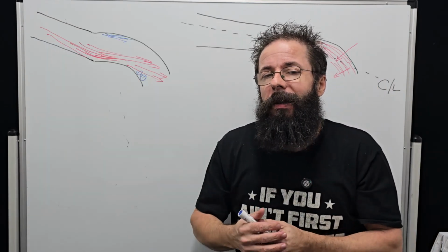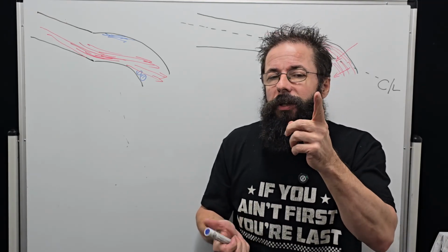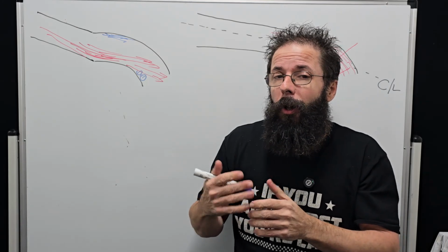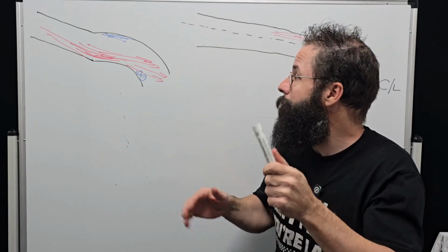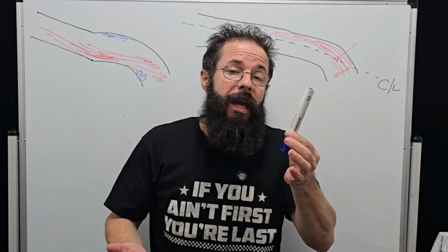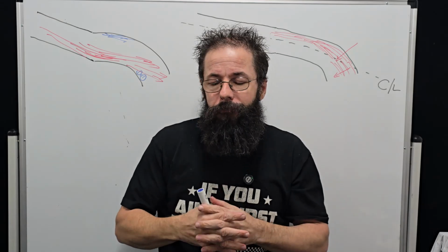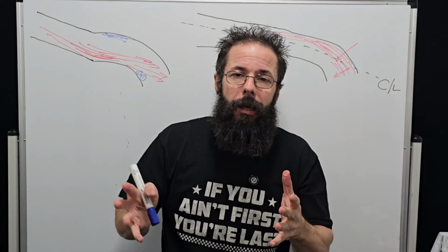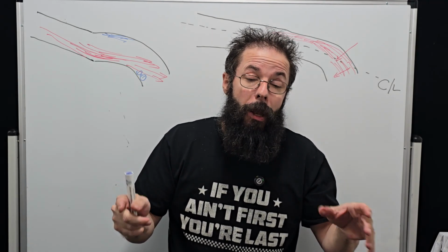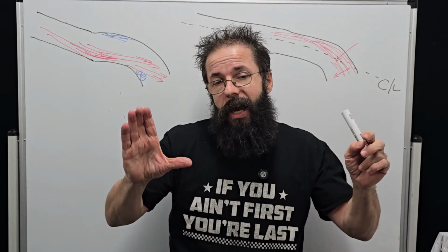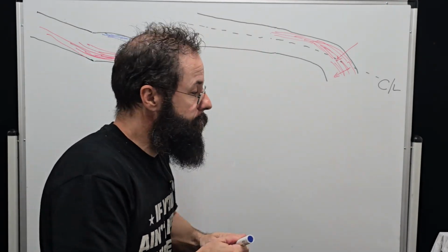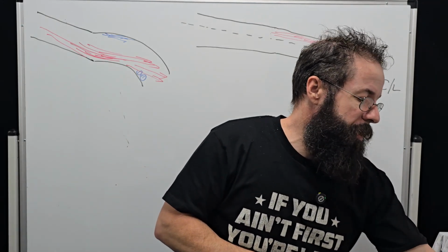This was the shape I was explaining the other day, and I'll see if I can share some photos from one of the super bikes on their new port design, exhaust port. But this is the gradient we're talking about, and what we tend to do, and you'll see this in a lot of big RPM stuff, you also see it in a lot of blower class racing now, we start to pitch the runners under the center line of the port, and not by a lot, but there's a few things that are going to happen here.